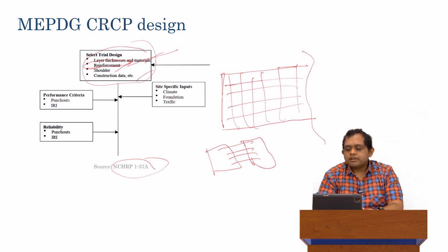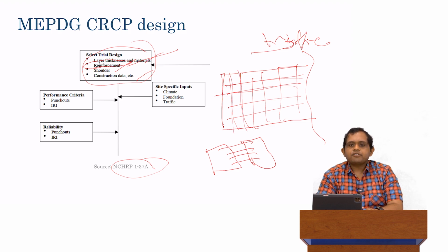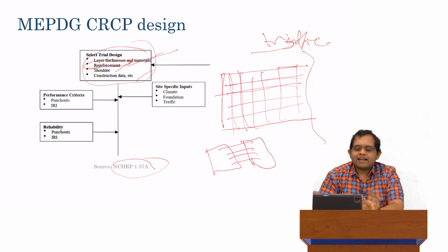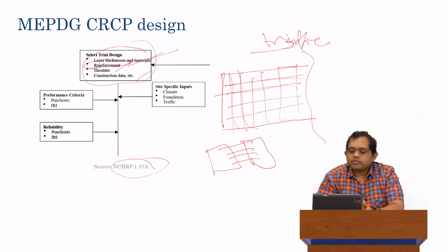We have this main reinforcement steel, which is in the traffic direction. So we have this main reinforcement steel and we have this primary reinforcement. We also have the secondary reinforcement, which is perpendicular. The purpose of the secondary reinforcement is simply to make sure the primary reinforcement does not move. But as far as design is concerned, the secondary reinforcement does not actually have any contribution. So we are very much concerned about the primary reinforcement.